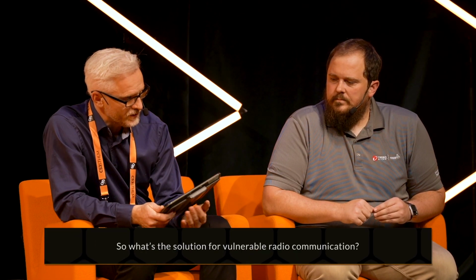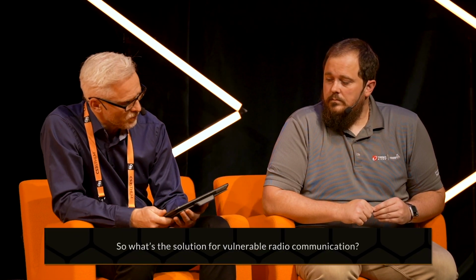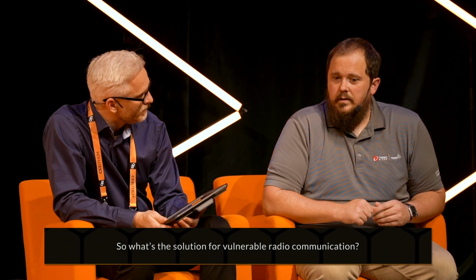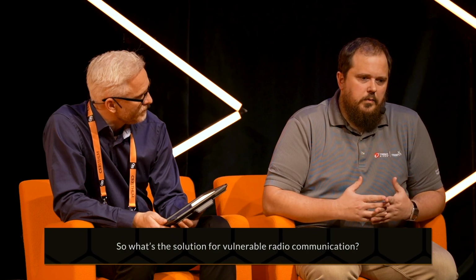So this kind of relates to another question that you already answered. What's the solution for vulnerable radio communication? To replace the equipment? You need to do a risk analysis of yourself to see if this is a risk to you. How far are you away from where somebody could sniff, see the signals? One of the best ways to do that is go around with a software-defined radio and see how far you are away from the crane, and can I actually see it and look at the packets? If I can receive them, then somebody can send them.